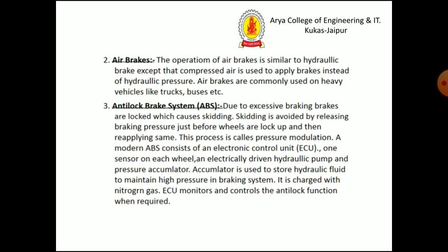Anti-lock brake systems. Due to excessive braking, brakes are locked, which causes skidding. Skidding is avoided by releasing braking pressure just before the wheels are locked up and then reapplying it. The process is called pressure modulation.